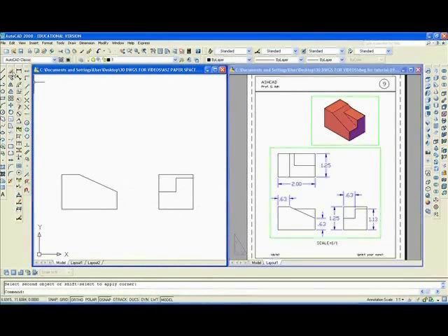but now we have to project over. So I'm going to copy this, drag it over here like so, escape. I'll do the fillet command here and extend, EX, enter, to this line, enter, that line.